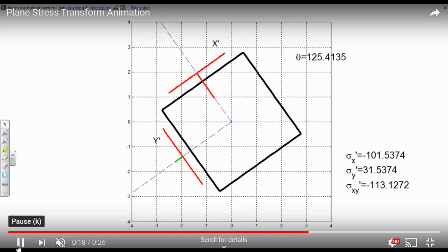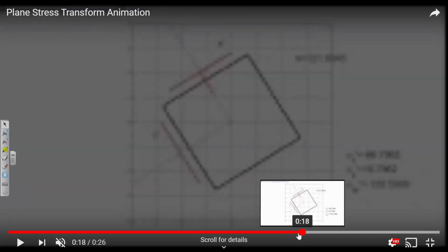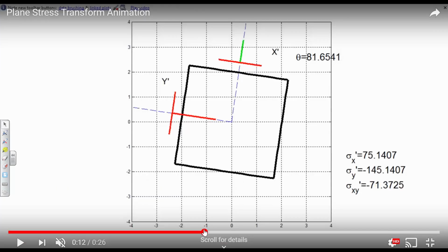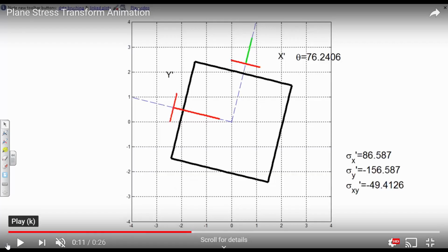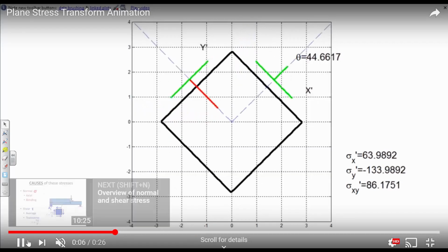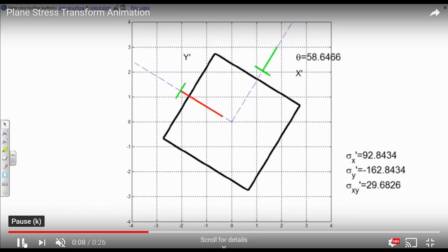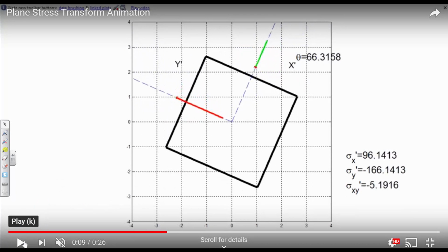Okay. All right. So what we say in a Mohr circle analysis is that when the shear stresses hit 0, about like that, your normal stresses reach their maximum. We have a name for that. We call those principal stresses. Okay? And usually when you're designing, you design looking at your principal stresses, your principal stresses being the worst case orientation of your stress state.